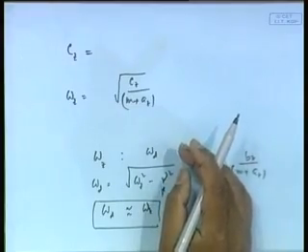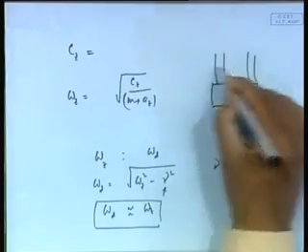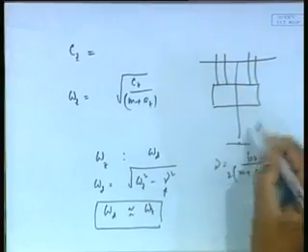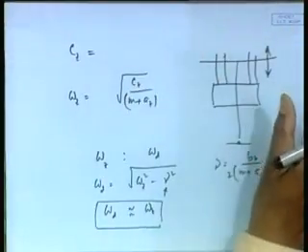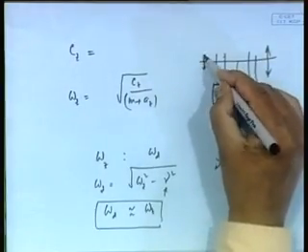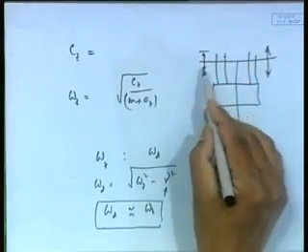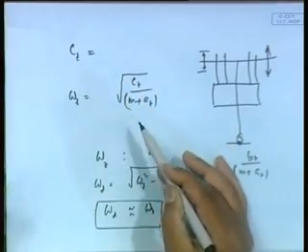especially for an offshore structure. An offshore structure is digging oil from somewhere, and is always stationary. If it begins to heave very large, you might stand here and not feel it, but this oil line is going to have tension. So, you actually cannot have oil exploration going on if the heave exceeds some value, say 3 meter or 2 meter or something like that. So, if it is heaving very largely, you end up having this problem. So, heave becomes very important. When will it be large? If the natural period meets the exciting period, remember. So, natural period becomes very important from the point of view of study.